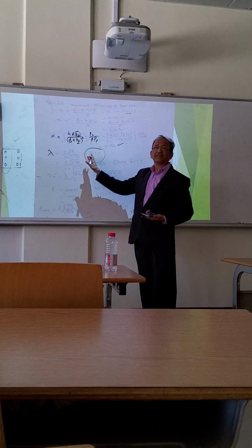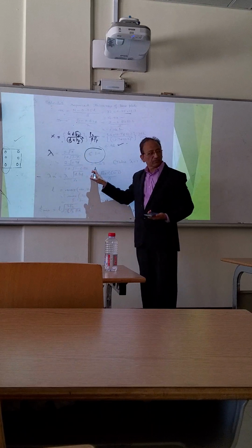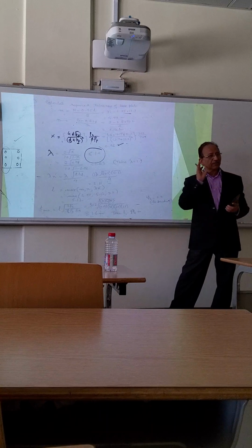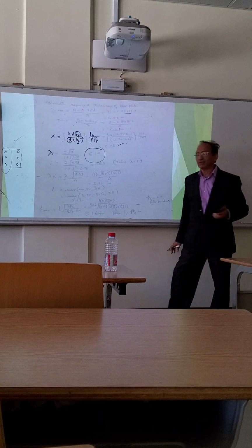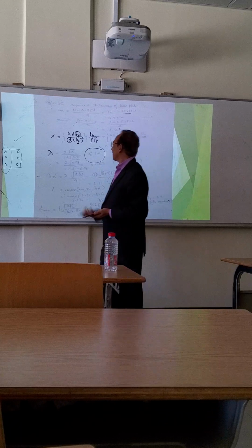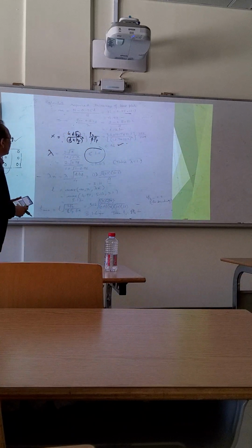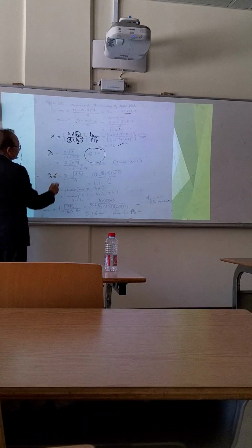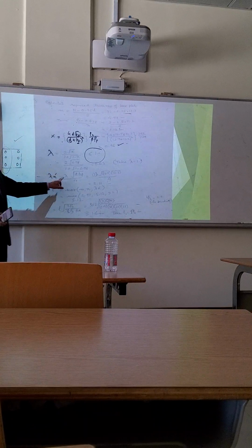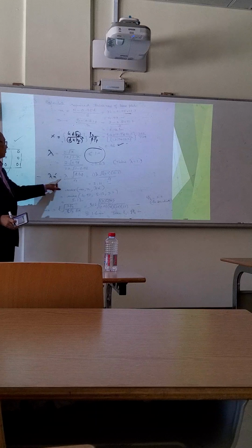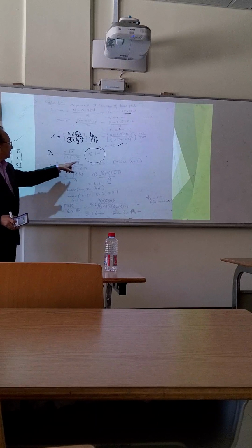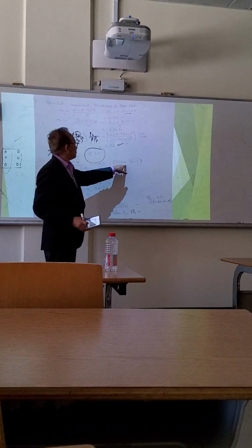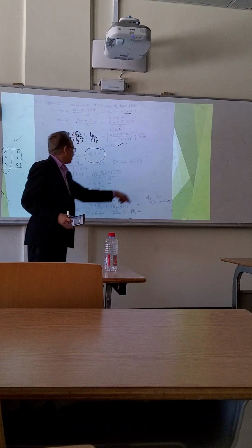Suppose you are getting 0.6, you will keep 0.6. If by calculation lambda is coming out to be 1.1, you will keep it as 1 maximum. So the maximum value of lambda is 1. After that calculation, you will find lambda n dash. Lambda we have taken as 1 because it was coming out to be 1.63.